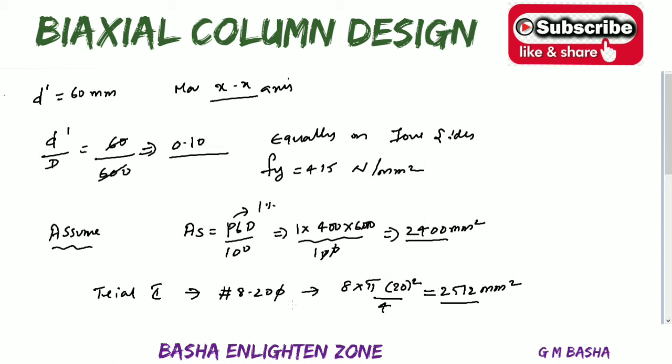I am taking a direct value like 8 bars of 20 mm, which is suited for this particular problem. We are starting from equal on 4 sides, which means we have to check 4 bars of 16, 4 bars of 20 dia, and again 8 bars of 16 dia, 8 bars of 20 dia. Calculate the individual area of the steel.